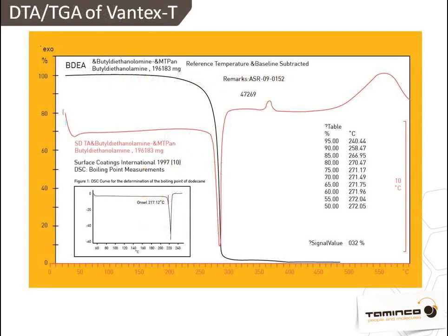Well, this is some volatility data from the metalworking field. This is an isothermal TGA method that's run at 81 degrees centigrade, 110 minutes. And we can see that a molecule like dicyclohexylamine has a reported boiling point of about 250 degrees C. Now, whether that's been correlated incorrectly or not is another matter. But it has a relatively high boiling point, yet it is completely volatile by this TGA method.